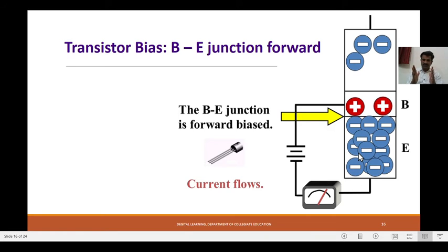The PN junction will get narrowed, and a narrowed junction means low resistance for the flow of current. Hence, most of the current will flow through the junction. The potential from the battery leads to the flow of charge carriers through the PN junction, so you can see a large current flowing through it.